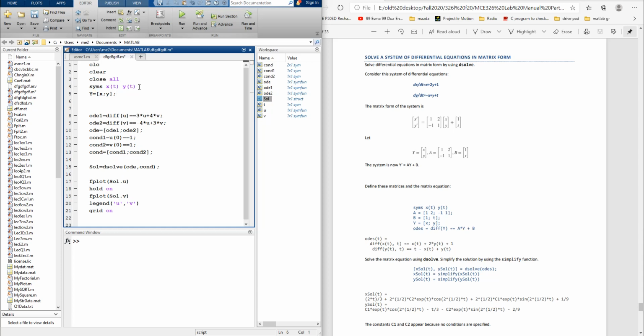And then we can say that A equals the matrix, we have 1, 2, semicolon, to go to the next line, minus 1, space 1. This is the value of A. And we need the value of B. B is a vector. We have 1, semicolon t. Sorry, this is not double equal, just one equal, like this. So this is the vector and matrix definitions.